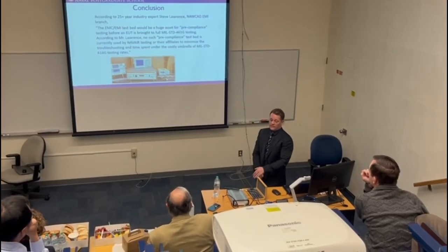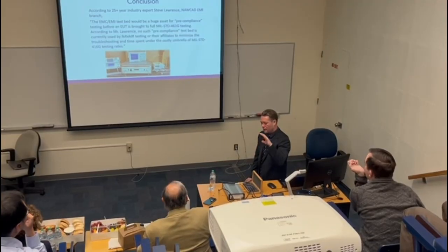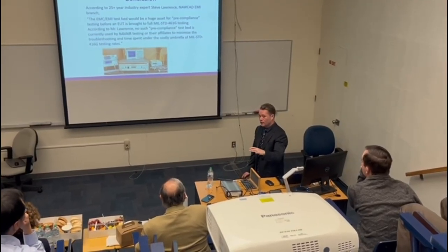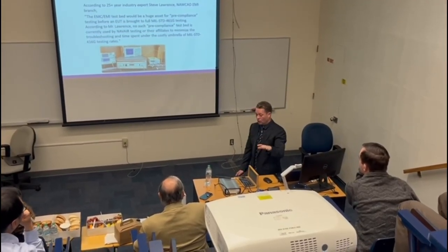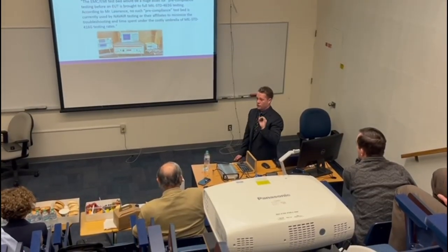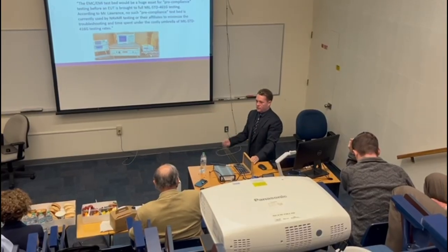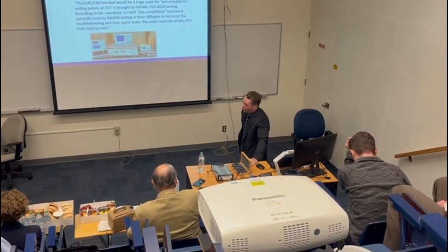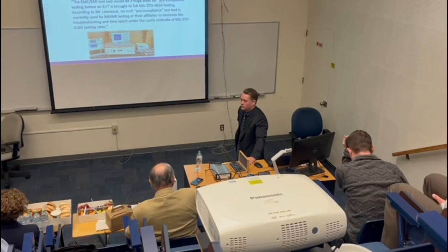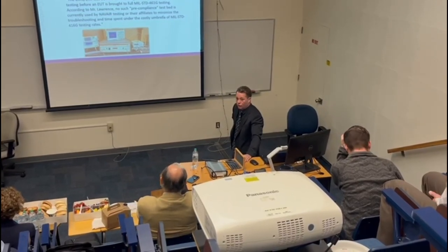Now, by no means am I saying ditch 461G. I'm saying this is a pre-compliance, post-compliance solution that adds so much knowledge about what your vulnerabilities are before you go to full manufacturing. You put these out in the field, and all of a sudden you're having all these issues that 461G said you should be good about. Well, the EMI environment has changed in those few years, so it's always good to do some sanity checks in-house and find vulnerabilities yourself.